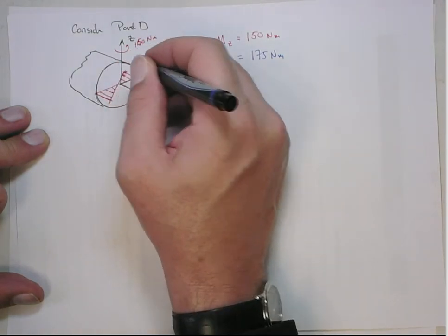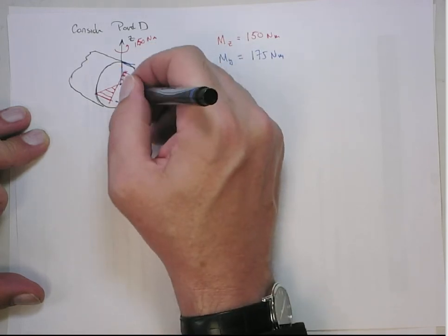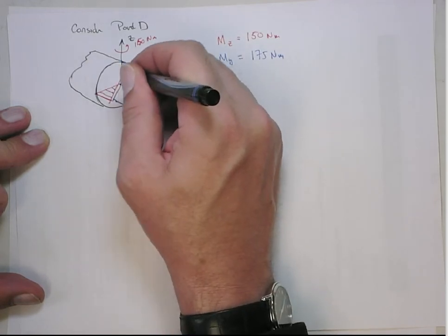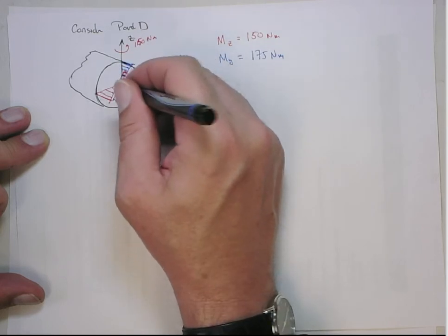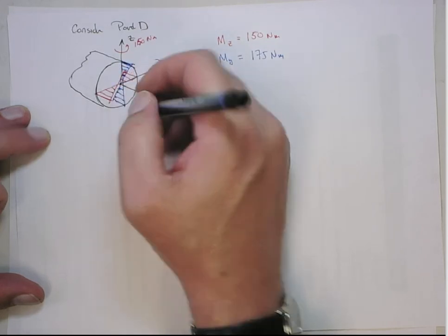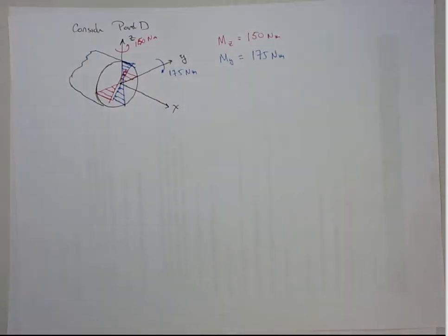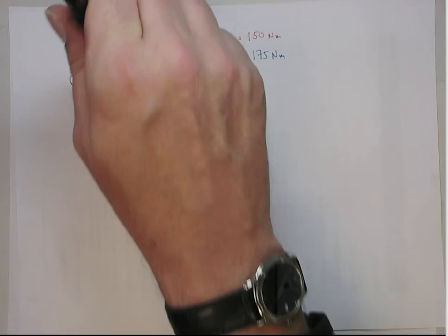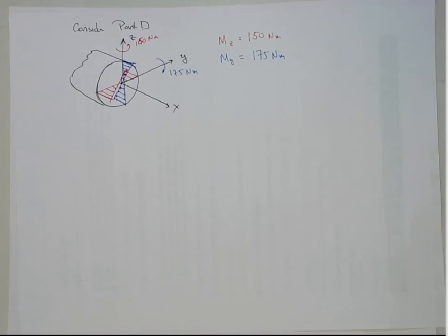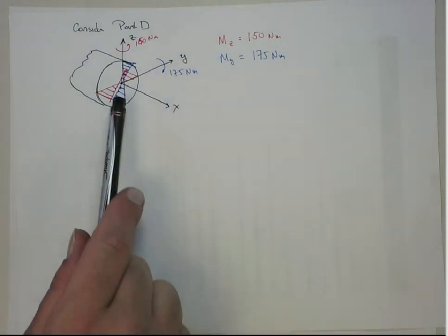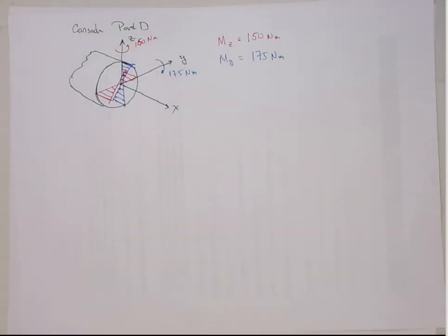So this one's going to come out in tension. This one's going to go in compression. So we can draw that. So somewhere on this face you're going to have a maximal, right? So this is kind of tricky. If you look at these 2 points, at 6 o'clock and at 12 o'clock, you're going to get no bending stress from the MZ.